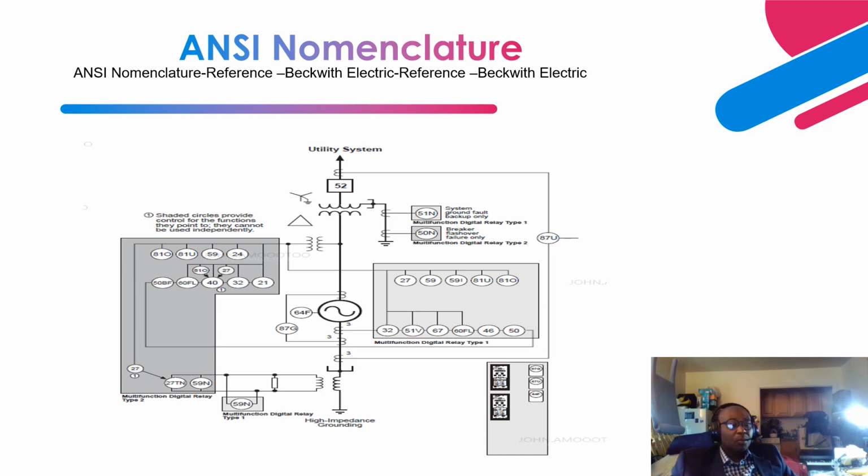Next is 50BF, and like I indicated, 50BF is a breaker failure element. Let's say this relay element is supposed to trip this unit breaker, and it fails to trip it. That is when this relay senses current flow through this breaker.